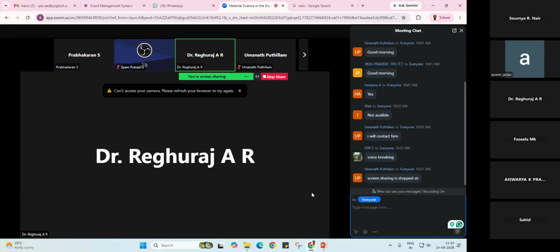You have to consider the spot diameter, right? Every parameter is very important while printing bio implants. There are many research articles available that will help you to select the proper process parameters, or you can do a single track analysis to find out the optimum process parameters to print the bio implants.